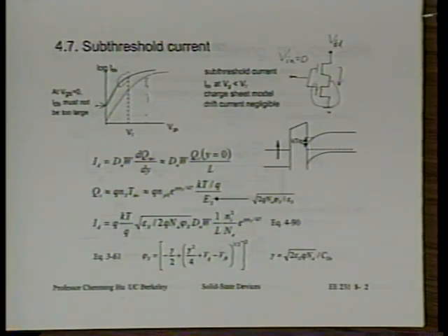Now, if we increase VDD, it turns out the power dissipation of the chip also increases because power is I times V, and each cycle of switching CMOS will take a certain current. So I is basically, in fact, I also increases with increasing VDD. So the dynamic power dissipation is going to be too large. So we cannot take that trade-off, higher VT and higher VDD. We don't want that. All right?